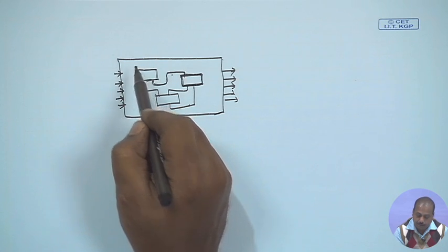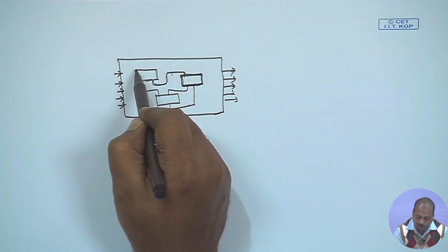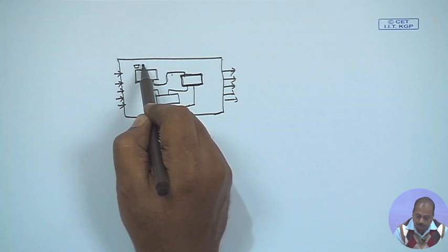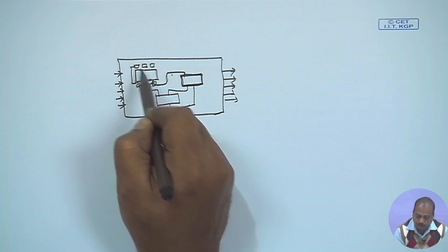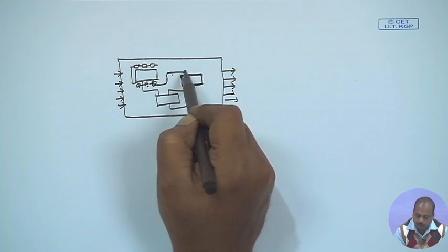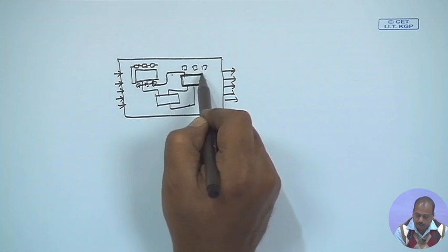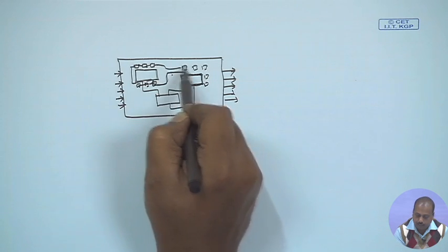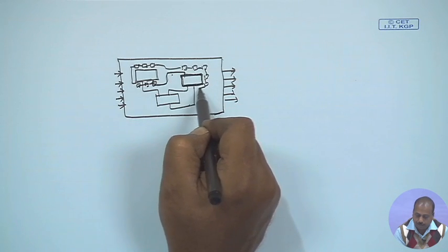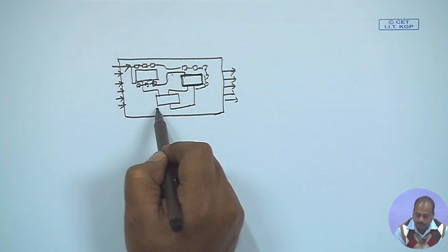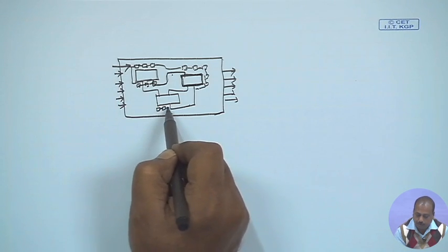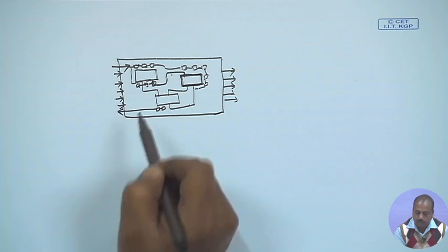So, what is done is that around every chip that we have, we have a chain of flip flops, connected in a chain like this. Similarly, this chip also has a chain of flip flops around it, and this chain is connected to this one, and ultimately it is connected from a system input. The last few flip flops are connected to the output.